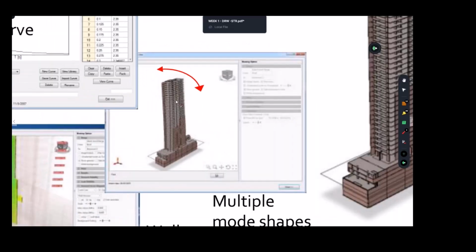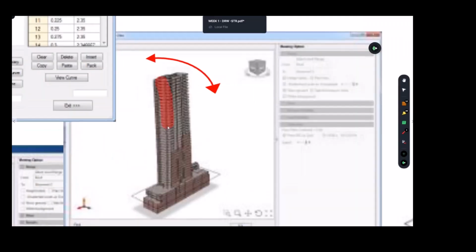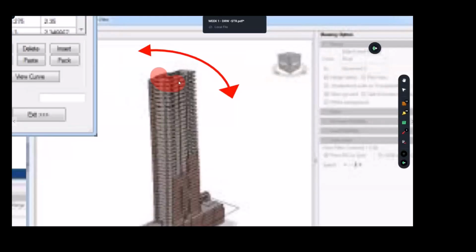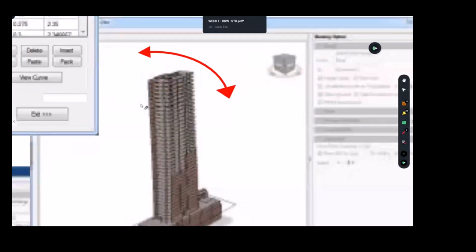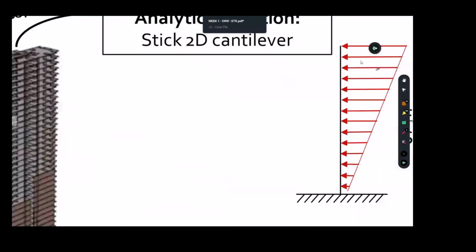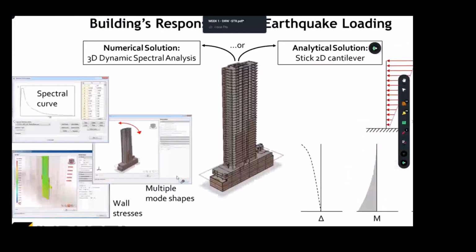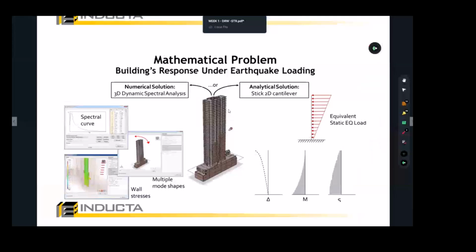This will definitely help you in case your core was sitting off the centroid. Then the software should be able, if things have been modeled correctly, to take those extra twisting torsion actions on the core. If this had to be done manually as well, and then you apply the analysis. So in a building like this, you can do the right side or the left side.